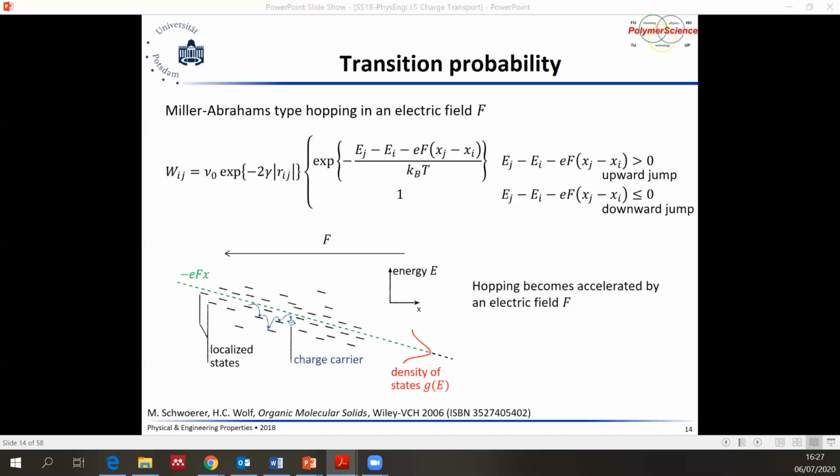Okay, so to remember, during macroscopic charge transport we have a large number of sites with different energetic and spatial distances, and this is felt or sampled by each charge carrier. This corresponds to a multiple trapping and detrapping mechanism of charge carriers, where the trapping time of every site is determined by the corresponding hopping distance and the energetic offset between each site.